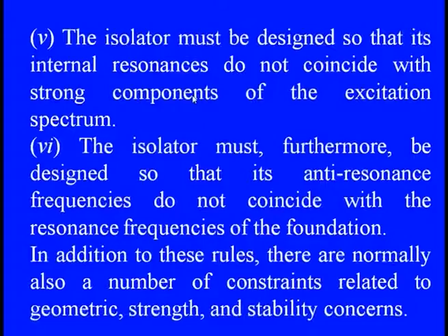Sixth point, the isolator must be designed in such a way that the anti-resonant frequency should not coincide, as we discussed, with the resonant frequency of the foundation, because if it coincides with the resonant frequency of this foundation, then we have a clear excitation of the highest level, and this excitation will transmit at a faster rate.